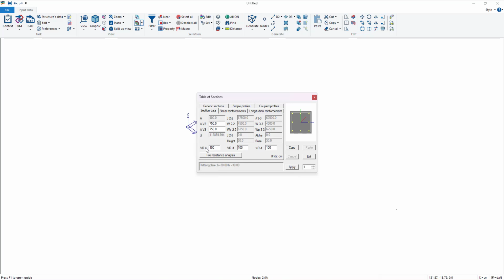This is an axial stiffness, flexural stiffness, and torsional stiffness. So if we have an element that in particular we don't want to work in the actual way for some reason, we can reduce this value from 100 to 1, something like that. But maybe this is something just advanced, so we're going to pass by.